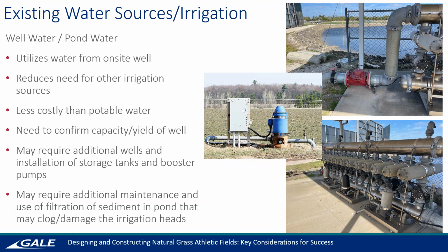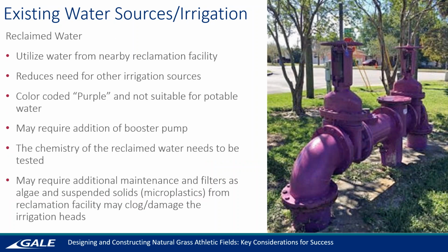The photos that you see here on the top right and bottom right are a baseball complex down in the Fort Myers area, a Major League Baseball spring training facility, and it's utilizing a stormwater pond next to it. But depending on whether you've had a recent rain event to that stormwater pond or something of that nature, you will need to include some type of maintenance and filtration and sediment devices within that system, so you're not clogging or causing any damage to your irrigation heads.